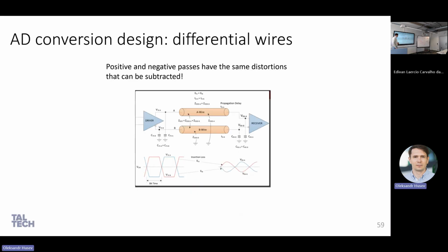So another approach, it's also something classical that most of you may know, differential measurements. Differential measurements means that you actually split or duplicate your signal to get a reversed one. And in this case, the impact of your noise can be subtracted, and you will measure only the useful signal. In theory, it works. In practice, you must be careful, because, for example, you can try to use this approach to measure with a microcontroller.